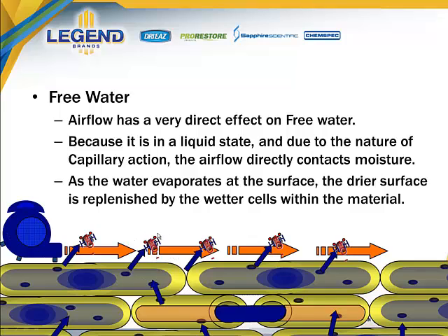We'll end up with something that we call, kind of loosely, a boundary layer, which would mean an area right at the surface of the material where air is not really moving that quickly, and the humidity begins to build because nothing is moving it away from the surface. This builds a vapor pressure at the surface, and it begins to impede additional evaporation from the building material.